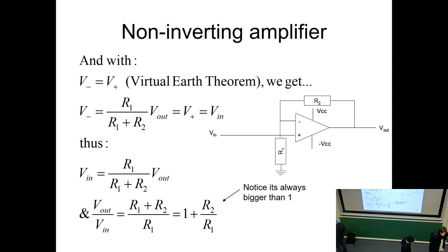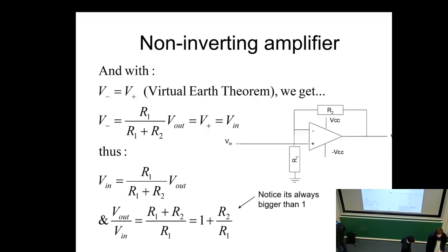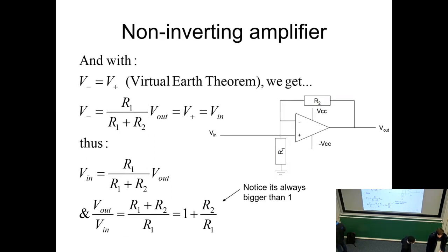What it's doing is that it sees a voltage here, and the op amp will adjust its output voltage up or down to affect this negative input, and it will adjust its output here to reduce the difference between these two to be as zero as it can, if it can possibly do it. If you get the connections around the wrong way, then it will adjust its output to try and minimise it, but the output's been connected wrong, so it'll just actually make it worse. That's positive feedback. Right, yeah.